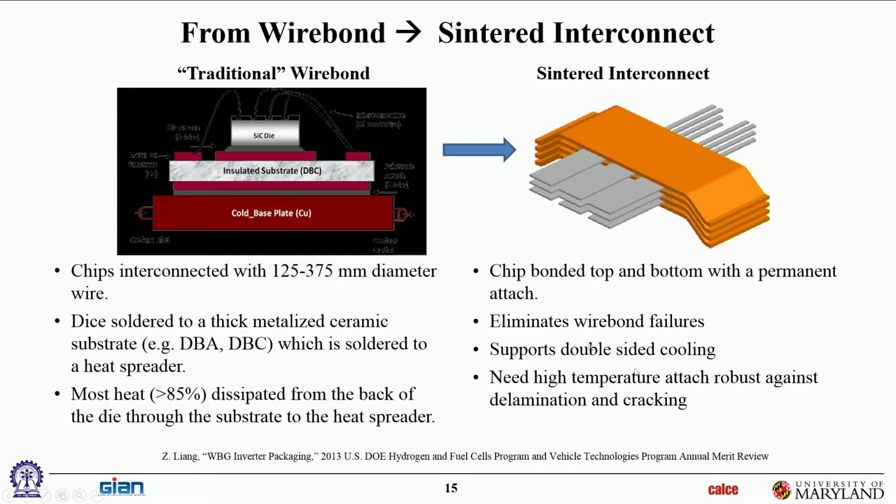Okay, and then so in these planar modules, we no longer use wire bonds, as I said. So the way we interconnect has now totally changed. We use some kind of a die-attached kind of material or diffusion bonded, solid-state diffusion bonded interconnections. And we bond connectors this way rather than use wire bonds. You can see it over there, instead of using wire bonds.